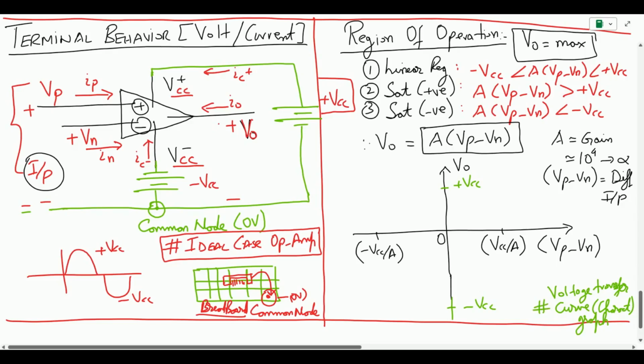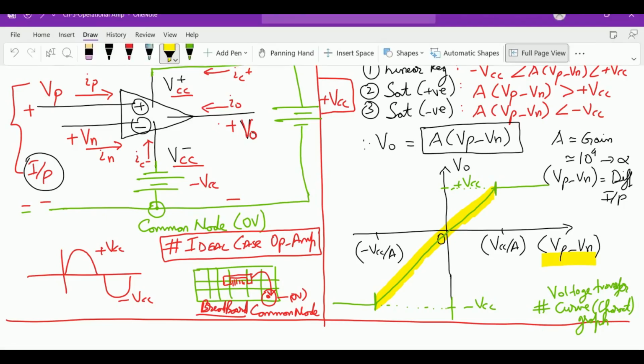So in our case, we want our system to behave linearly, which means our circuit is going to behave something like this, and after that it is going to become saturated. So this is the point where it becomes saturated. This is associated over here and this is associated over here. These are the boundaries for the op amp. Basically this is the linear region where the amplification is happening. This linear line is where we want to keep our operational amplifier working, and as you can see, the relationship is linearly increasing. For whatever input we have, we get a linear increase in its output.